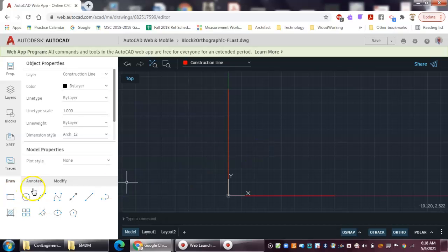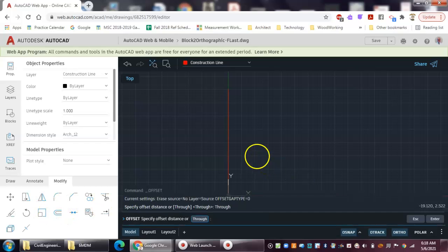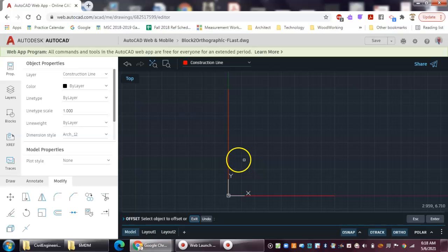So now if you recall, creating our 9 lines, we're going to use the offset tool, and we're setting these 9 lines based on the dimensions, the biggest dimensions on the part. In this case, our part measures 6 inches by 3 inches by 1.5. So my first width is going to be 6. So I'm going to move it over and hit 6 and enter.